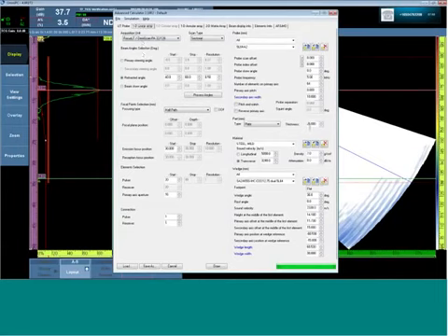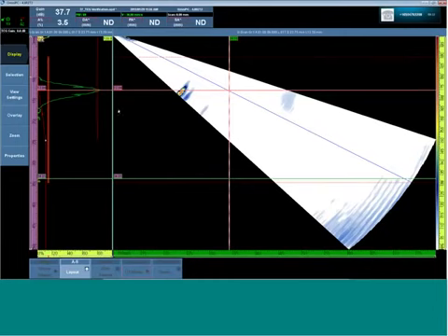Probe, material, and we'll see more information than just material velocity for higher functions used in other software. Wedge identified. Once the hardware is all entered, I can start asking for beam information that will change the size, shape, focus, and angle of all of the focal laws.